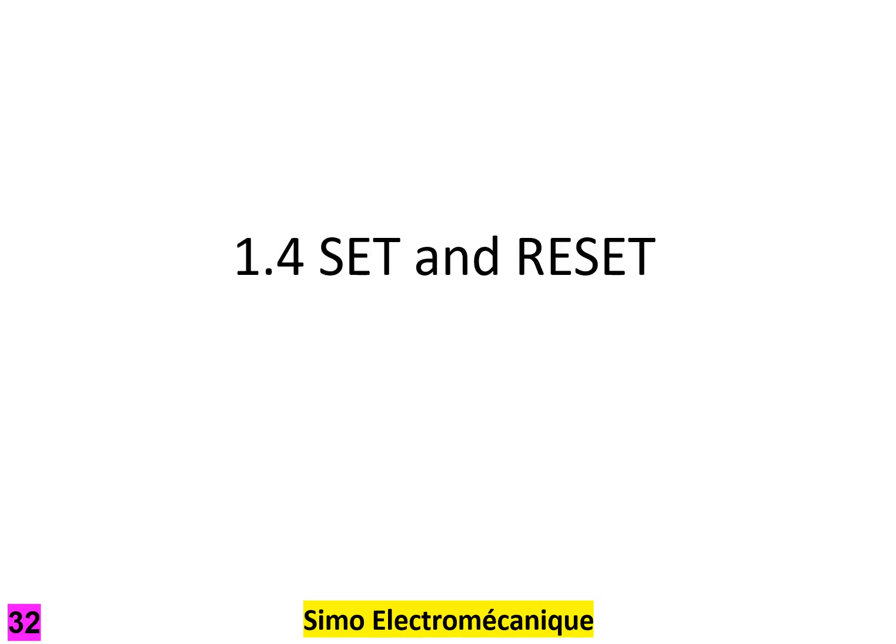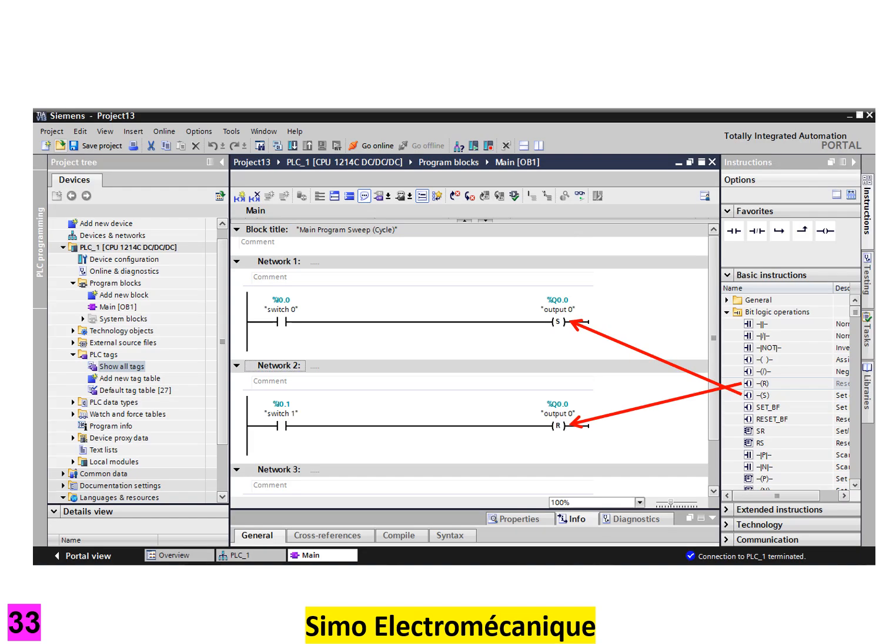Set and reset. On the program we have looked at so far, the outputs immediately change when the input changes. Often we don't want this to happen. We might want an output to switch on and stay on until something else switches it off. The program here demonstrates how to do this with the set and reset commands.